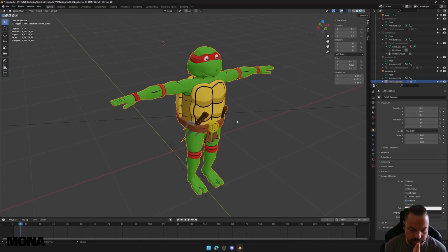That said, I think 3D objects by AI are a really good reference point at this point. Once again, it'll replace everyone's jobs soon, but for now, 3D assets are still good reference. So if I was going to use Stability AI or Luma or any of those, I would make the asset, get it how I want, and then use that as reference to make the high quality asset. And if the asset is high quality enough, then you can use that as the, let's say, high polygon asset, and then bake that information onto a low polygon asset.